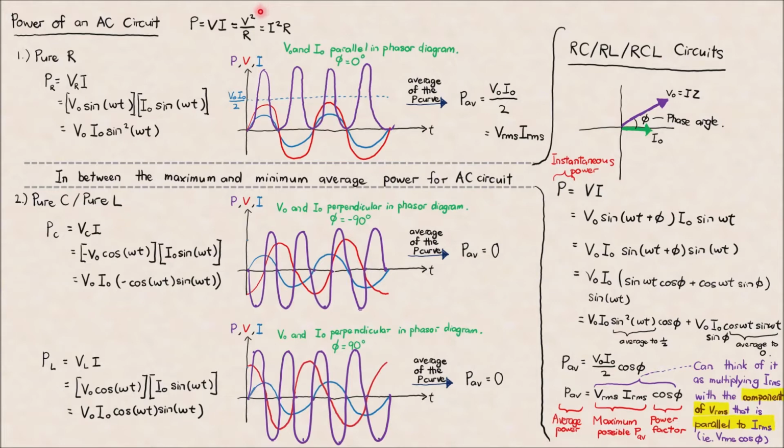In chapter 3, DC circuit, we know that the voltage across any circuit component will be constant with time. The current flowing through any circuit component will also be constant with time. Different branches can have different current, but as time passes, the current and the voltage should be constant. So if V is constant and I is constant, you can assume that the power you obtain will be constant as well. Resistance is the same thing. If you are not changing the temperature, the resistivity, the length, or the cross-sectional area, you should have constant resistance as well. So in DC, you always expect the power to be constant with time. It is not changing with time.